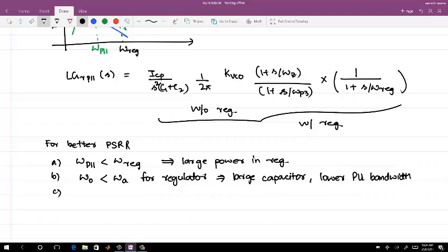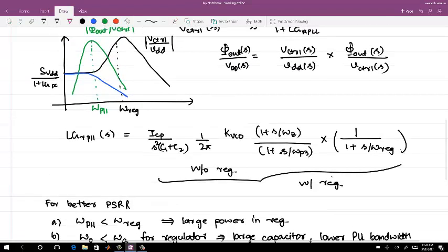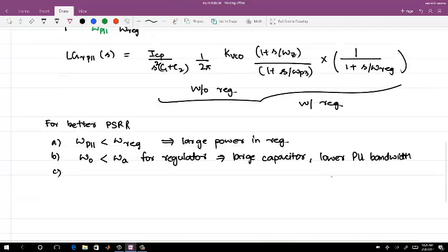Okay. Now, in another way, if you lower the PLL bandwidth, even this curve will change, right? So you may have something now like this. So this can happen. These are all the translations which we are looking at. One is we are looking at these two translations, right? Now, if you have a lower PLL bandwidth, what's the trade-off? Synchronization trades.